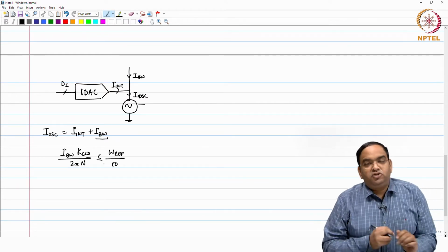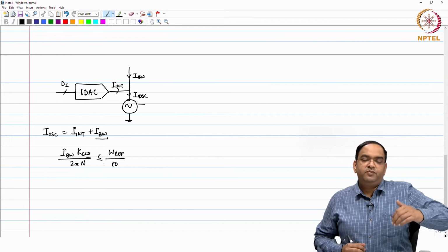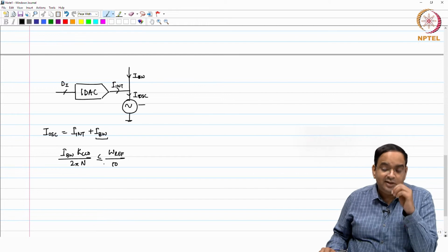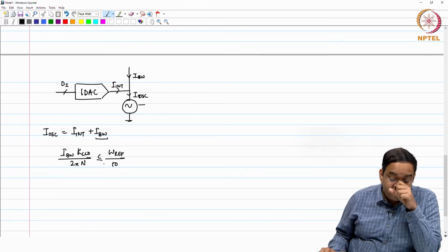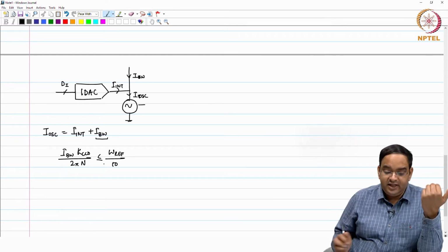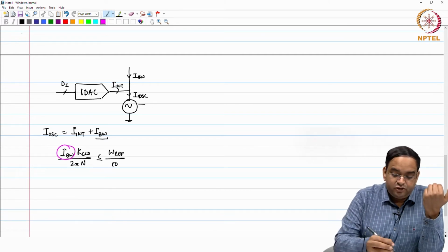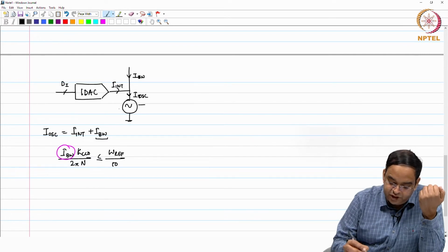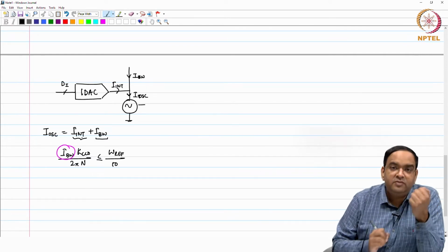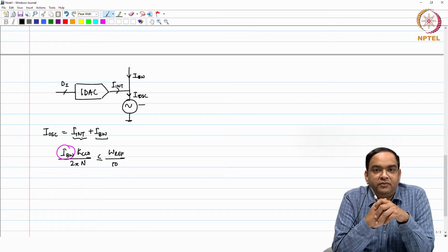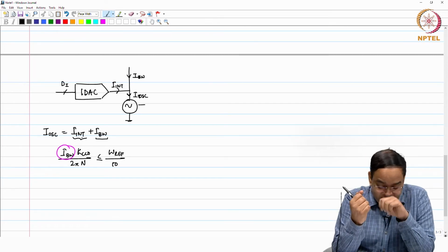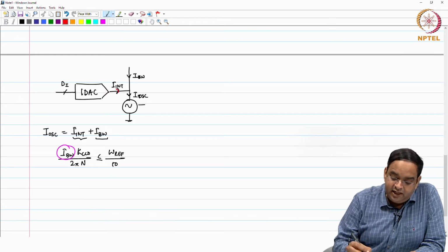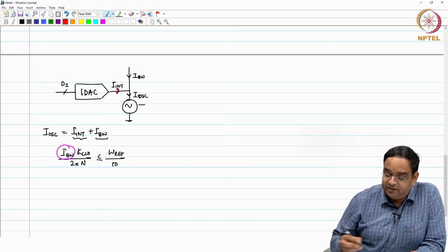This is going to limit your I bandwidth, and quite often it may not be possible to have the optimized bandwidth; your actual bandwidth may be even lesser than that. So, I bandwidth is limited. For the oscillator to oscillate at a given frequency, a major portion of the total current comes from I integral. Now, when the major current is coming from this I int path, the problem is that all this current is based on the DAC which we are using.